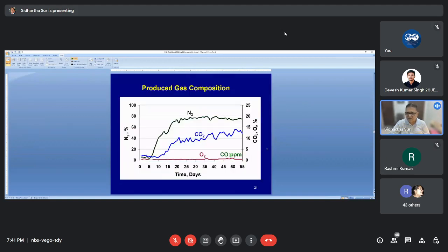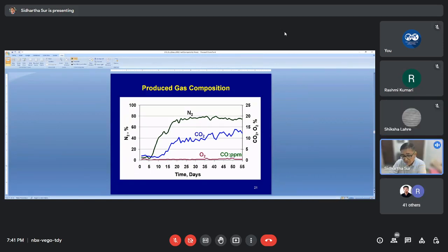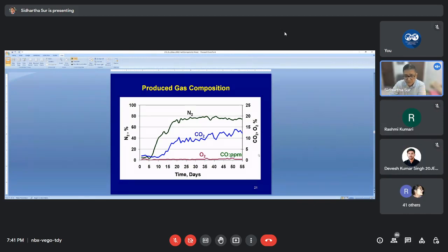So this is the evidence in the field. How do you know combustion has taken place? Your management goes on asking this question when air injection is started. So watch out in the production wells for the gas composition. Nitrogen comes immediately from injection; this is a real case with a distance of around 150 meters between injector and producer. You can see nitrogen coming up so early, very quickly building up, because nitrogen is inert.